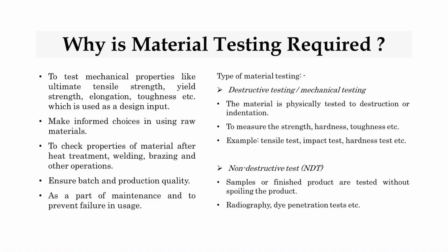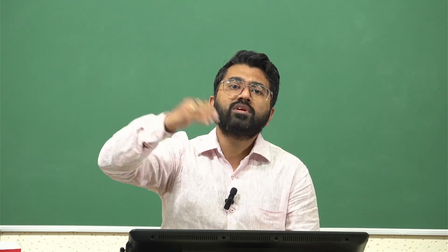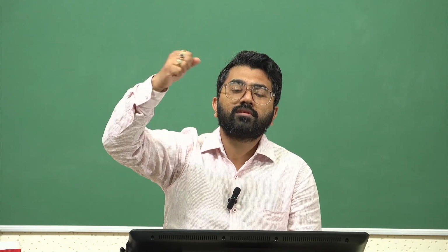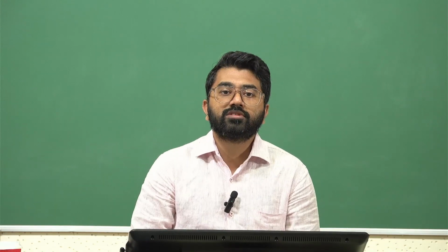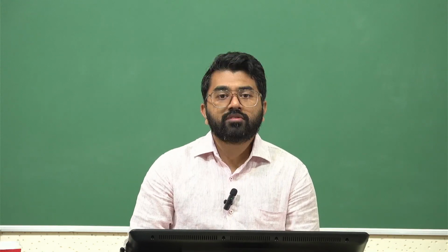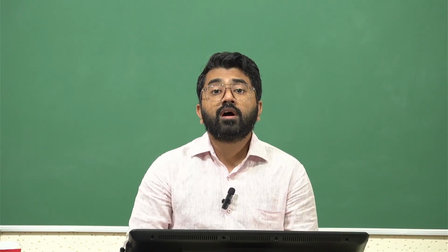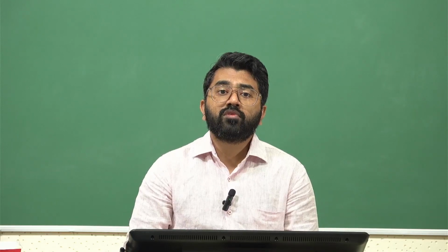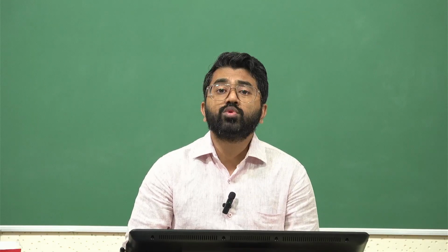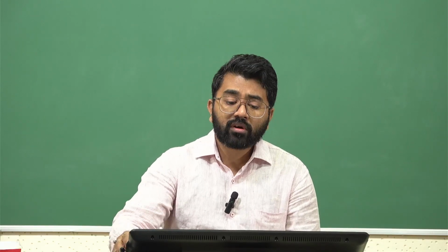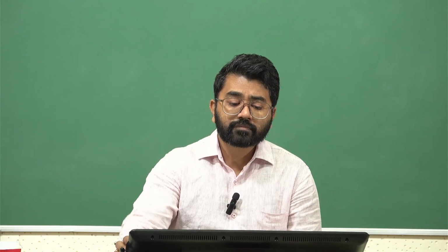Some techniques such as radiography, dye penetration tests, these are sometimes also used for non-destructive testing. Also, tensile and compressive tests can be non-destructive. They do not have to be carried forward till the ultimate point when it breaks, or when you push that it completely crushes, right? So destructive and non-destructive has a thin line. You can do non-destructive tests even with the machines where you can perform destructive tests depending on the load limits and other things, and you have some other techniques as well which you can implement, right? So these are broader reasons for doing material testing again.